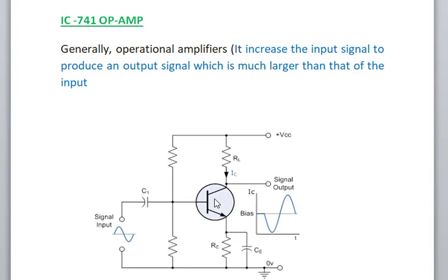It is an NPN transistor. You know already the emitter is always connected in forward bias. Base also is always connected in forward bias. Collector is always connected in reverse bias. What is forward bias? A p-type material is fed with positive polarity, or an n-type semiconductor material is fed with negative polarity. This type of biasing is known as forward biasing.